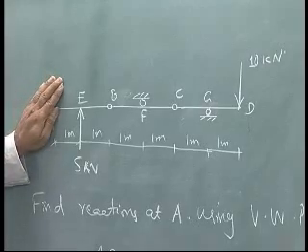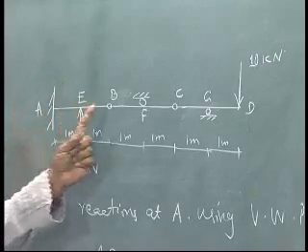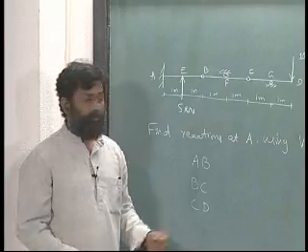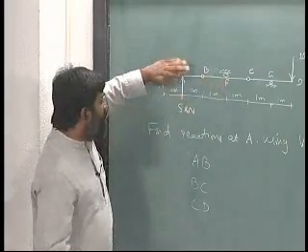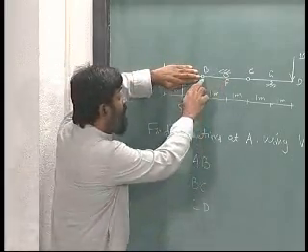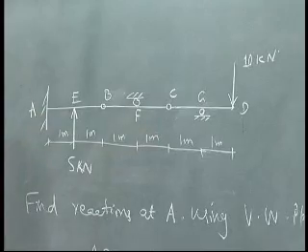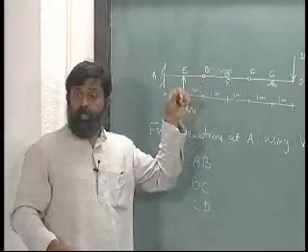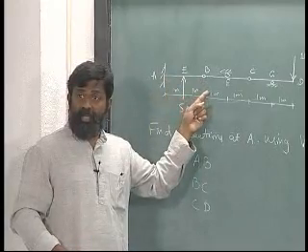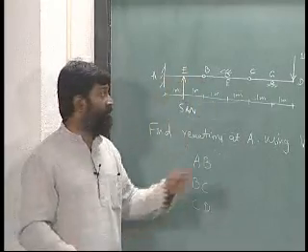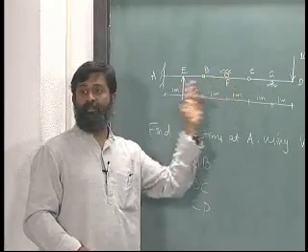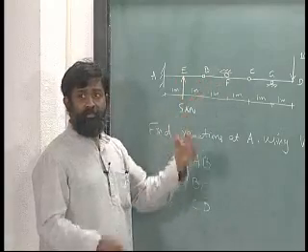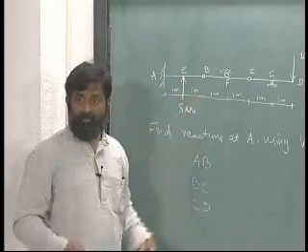Let us come back to this A later. Between AB and BC, what do I know? Supposing I fix AB, the displacement of B in BC is fixed, alright. So, it offers a constraint at B, whatever is the displacement of AB at B, it is the same displacement of B at BC, correct. And therefore, can it rotate between them? The rotation between them is allowed, right.